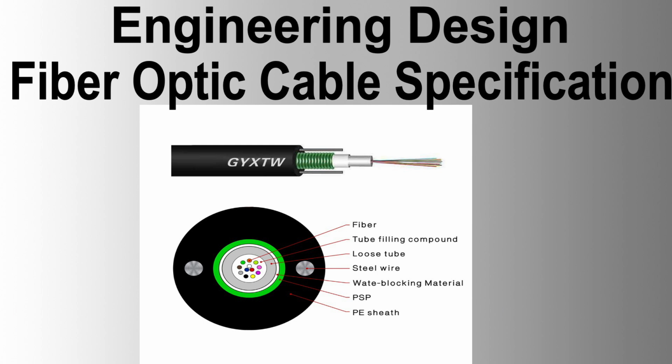Superabsorbent polymer materials. Water blocking. Cables must be water blocked with superabsorbent polymer water blocking yarns, tapes, and/or binders. Superabsorbent coatings on cable elements are not acceptable. The materials must be safe, easy to remove, and require no special handling or solvents. Strength yarns. Material. The strength yarns for polyethylene sheath cables shall be aramid yarns.